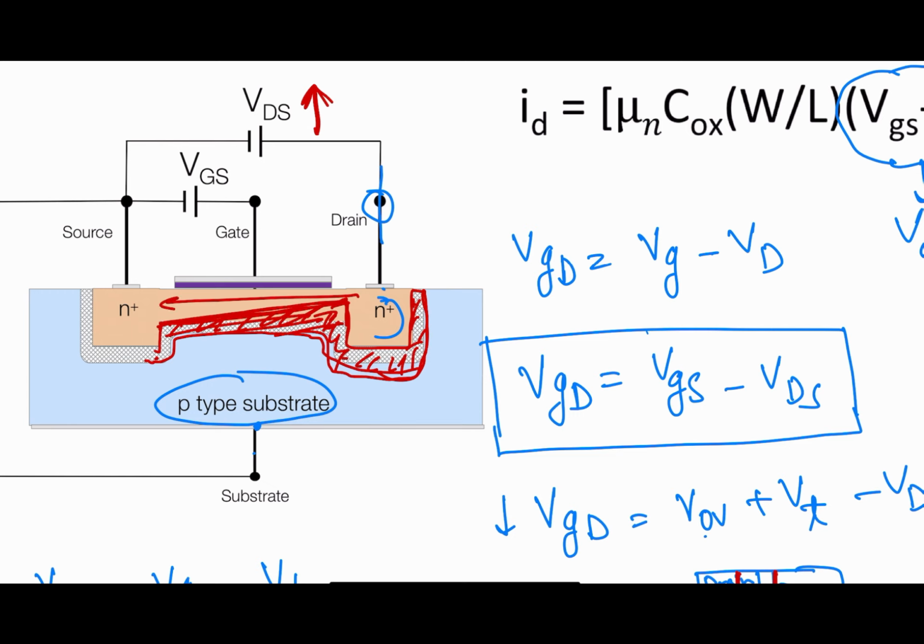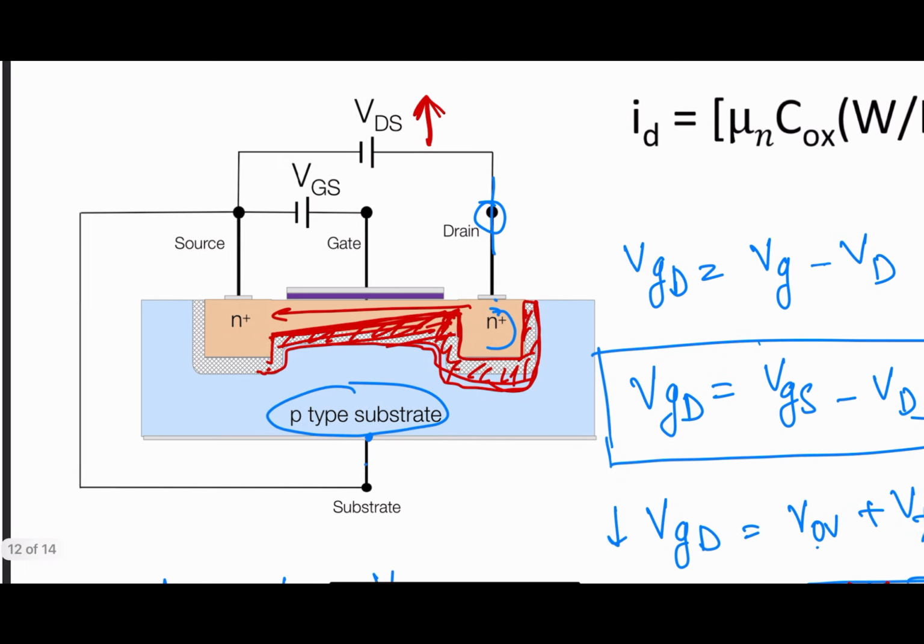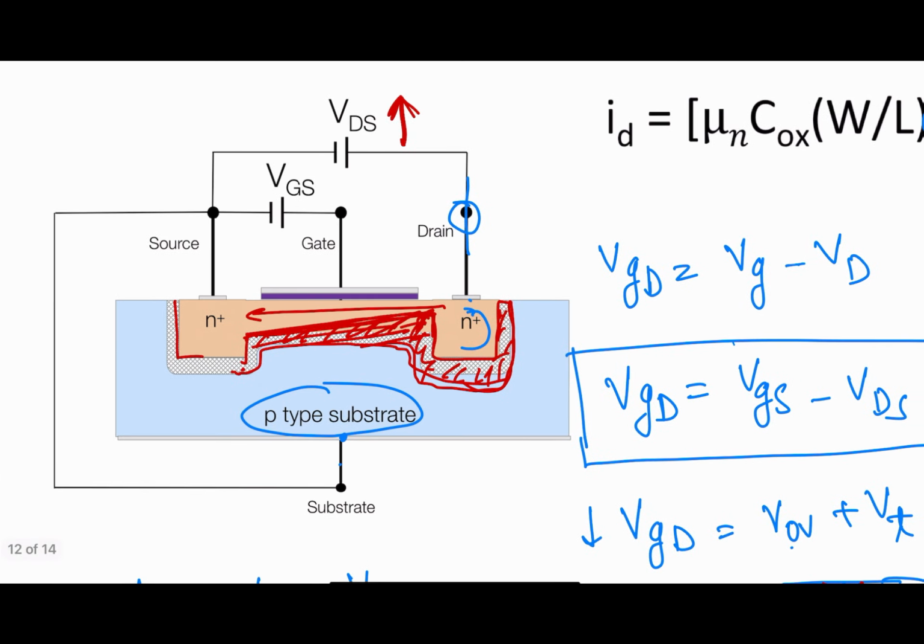So that means electron flow in this channel. So that means the channel is tapered, okay? The channel is tapered, so the channel width will be lower here. I will explain how this will affect the current. But maybe in your mind, one question will be there: why on this side is the depletion region the same? Why will the depletion not increase on this side?